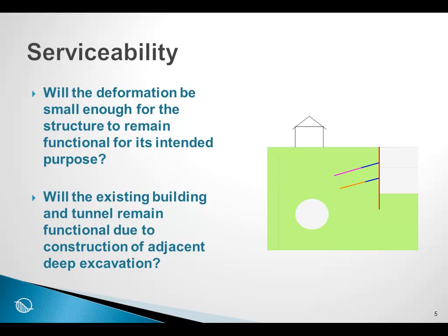When we make this deep excavation, tieback excavation, will it be such that the deformation of the building will not be so high that we can no longer close the windows or the doors, for example? Because if the deformations reach the point where this happens, then the building is no longer functional. The building may not have fallen down, but it is not functional.